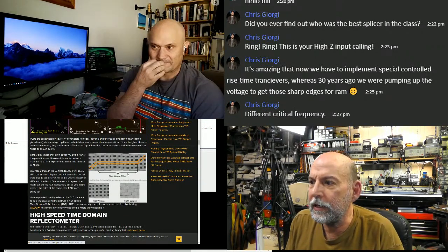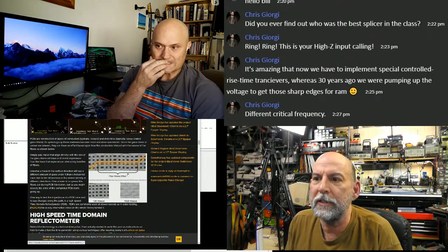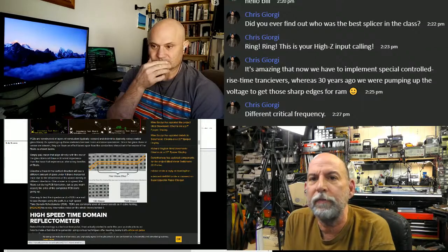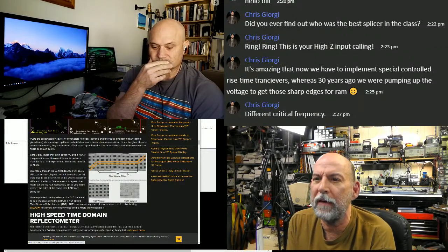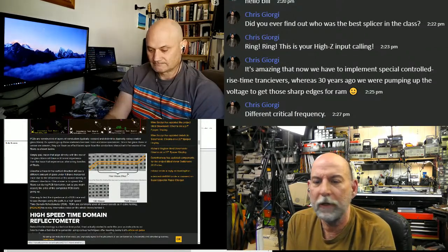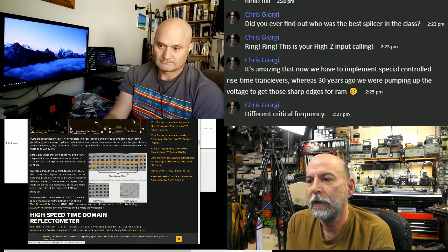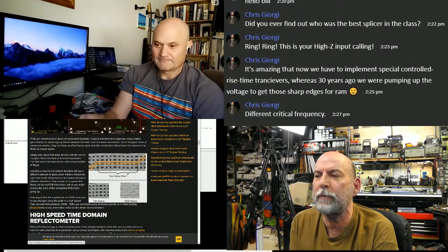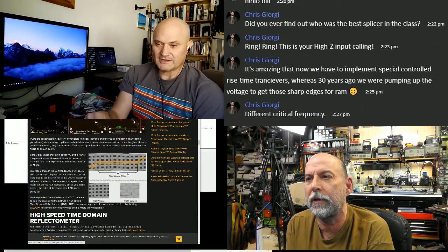But in the old days, I used to like LS because compared to AS or F, you were asking for trouble if you used one of those. And I have put an F part into production, but it was because nothing else would do. But yeah, you want to use the slowest family that works is a good rule of thumb.